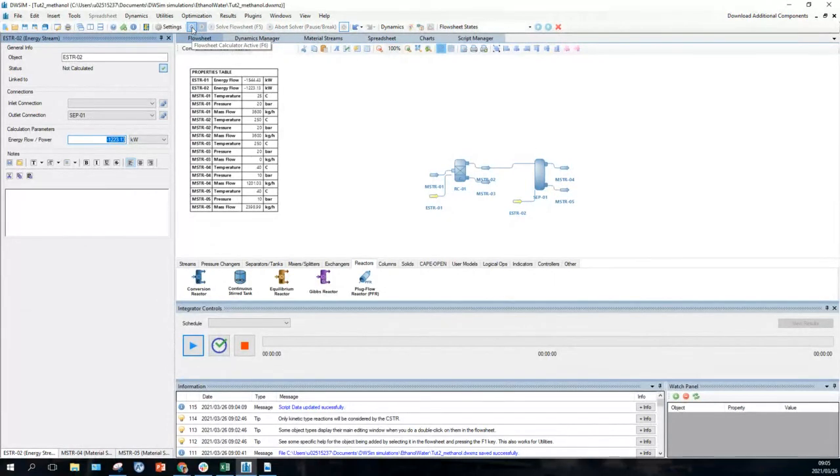And in that case, you want to switch off this thing. You can switch off flow sheet calculator active or not. Oh wait, I think it's that thing. You switch it off. So then for solve, there's a way of switching off the automatic solving. I wonder if that's it. Abort solver. But yeah, as soon as you've got a complex flow sheet, it might take too long and really impede your progress, because it's taking more than 0.12 seconds to solve the flow sheet.